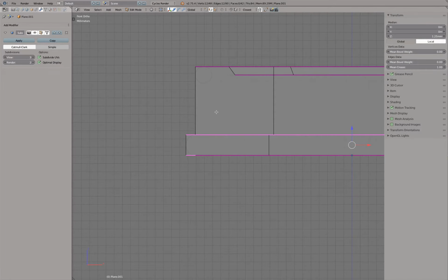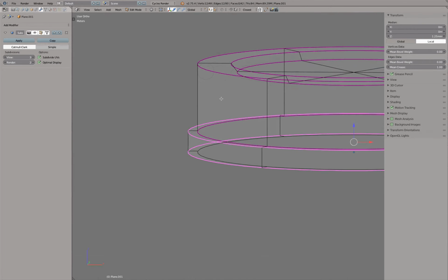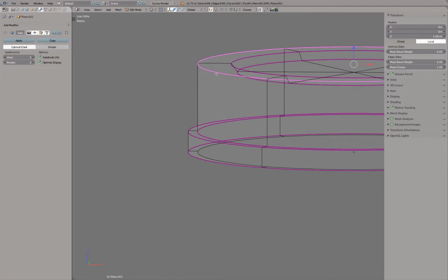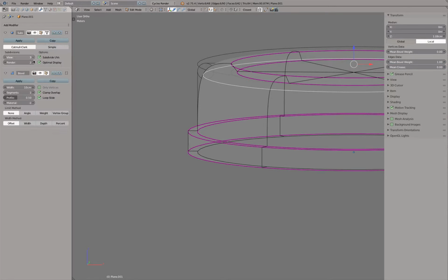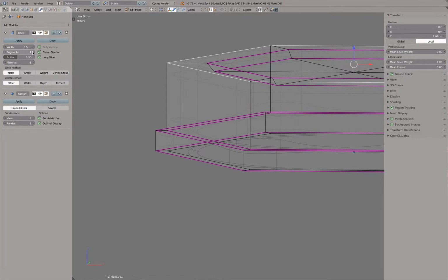So now we can actually be a little bit creative with the way how we style everything. So this edge I'm going to soft, and actually here add a crease again with the bevel command. So let's move this one up 1 millimeter, maybe 5 there, and the weight only.